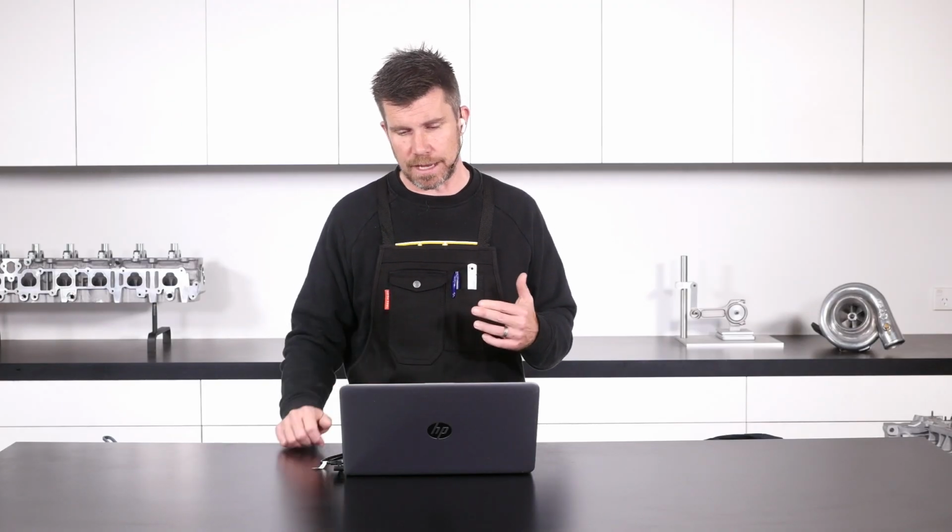It does make it a little bit tricky if we have a twin scroll turbocharger where, as I sort of mentioned previously on our FD RX7, that's the exact scenario we've got. A lot of people will just fit a single exhaust manifold back pressure sensor, and within rights we should be able to expect the pressure to be relatively consistent from one scroll to the other. That doesn't always pan out though, which is why I'm personally interested in seeing if we do have any discrepancies there.